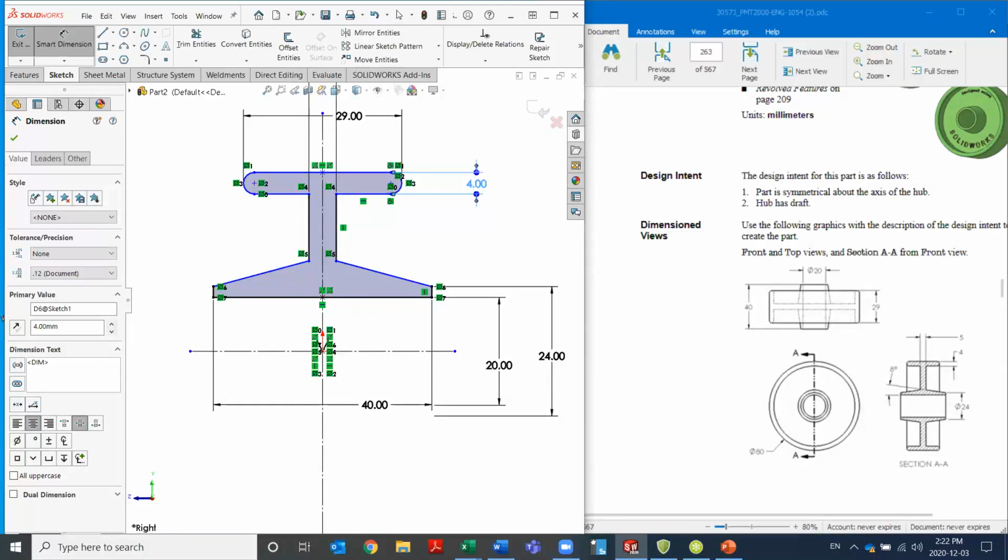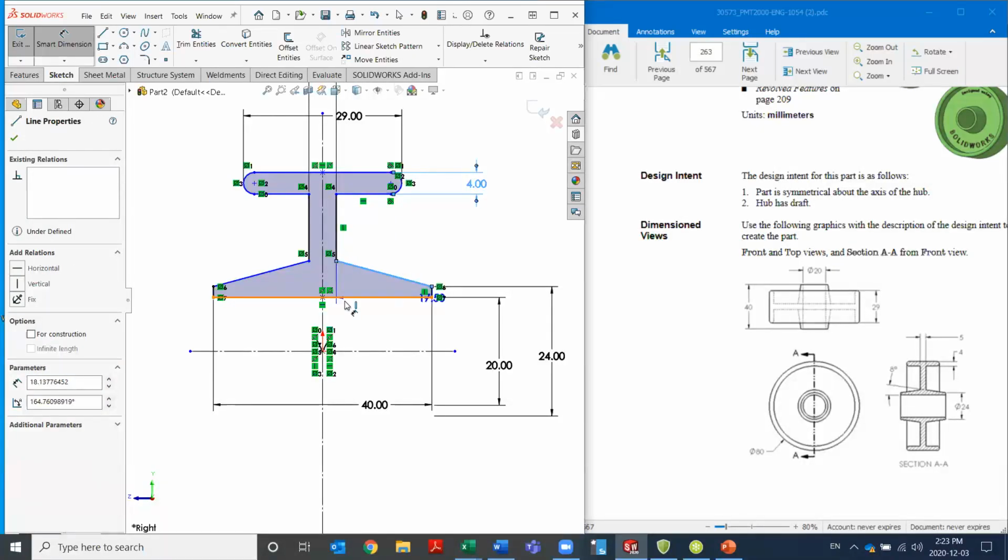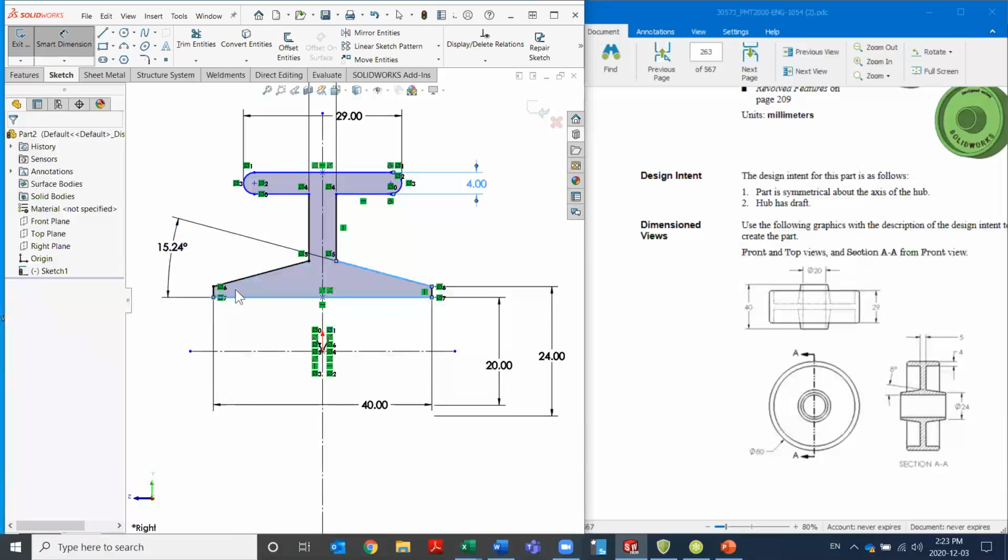Now, it can be a little bit tricky to decide how to get that 8 degrees because with our smart dimensions, they'll flip around a little bit. What I always like to do is say, okay, if they're taking a dimension here and here, I'm going to grab those same edges. So the edge on the inside here and the far edge here and put my dimension here. That way I've got kind of exactly what they've got. So coming back in here, that means this line and this line, and we'll make these 8 degrees.